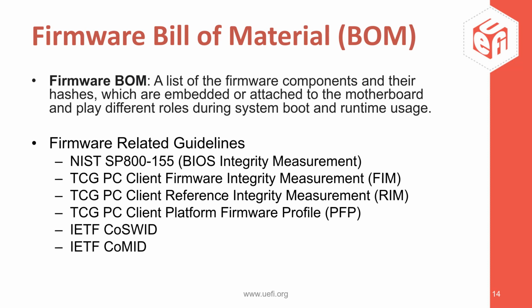There are several sets of specifications and standards which are available today. There's the draft NIST SP 800-155 BIOS integrity measurement special publication. TCG published earlier this year the TCG PC Client Firmware Integrity Measurement specification and also the TCG PC Client Reference Integrity Measurement information model. And I'm sure many of you are familiar with the TCG PC Client Platform Firmware Profile. There also exist some IETF standards: a standard for a concise SWID tag and a CoMID.